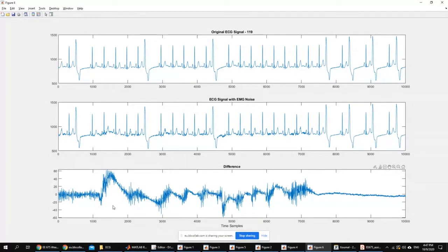If I have a low frequency noise, then I have to have a high pass filter. If I have high frequency noise, then I have to have a low pass filter, and so on. So just going in the right direction after you chose your hypothesis will be very crucial.